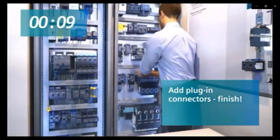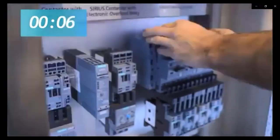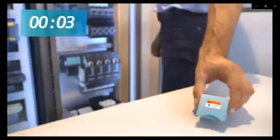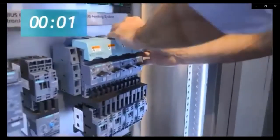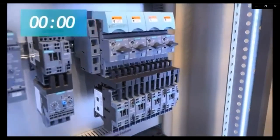Another advantage, the infeed system allows hot swapping of the equipment. This means you can change the devices while power is connected. Of course, the power is not under load. It remains safe to touch during the replacement, even when the starter has been removed.